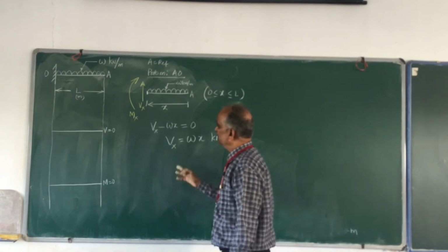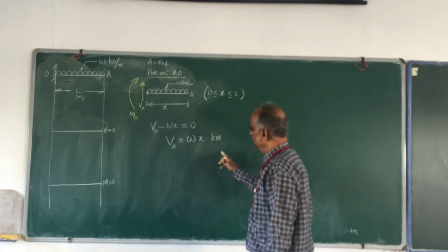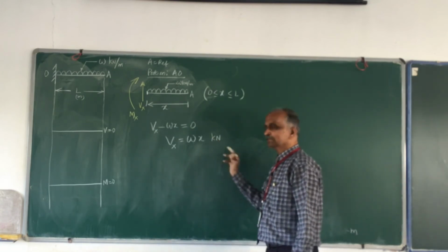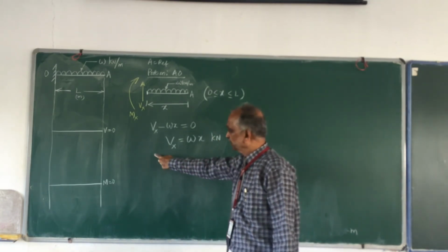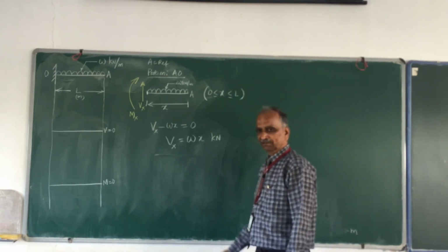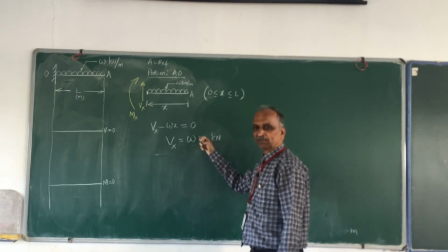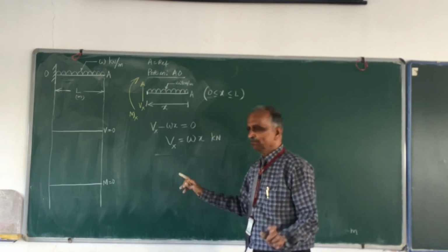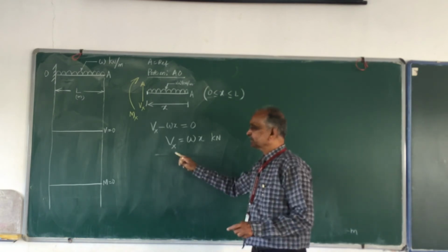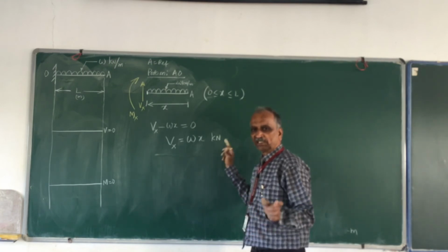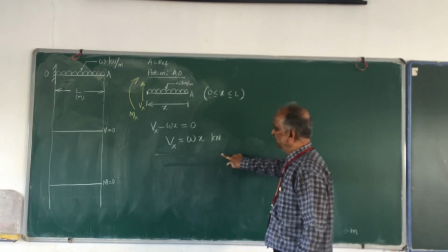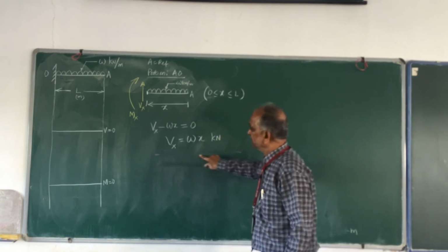Okay, come back here. Shear force. Observe. Is it constant? It is not constant because I have x here. So it is varying. That's the first observation. Shear force varies. How does it vary? I have only what power of x? X raised to 1 only. So do you agree that shear force varies linearly? Shear force varies according to a straight line. Please write down: straight line variation of the shear force.